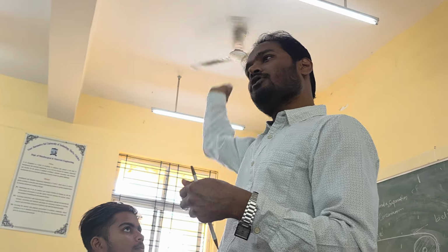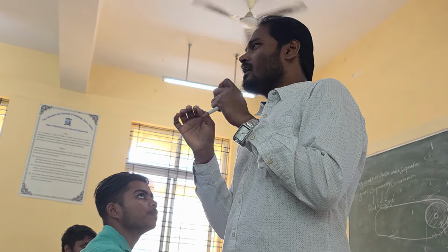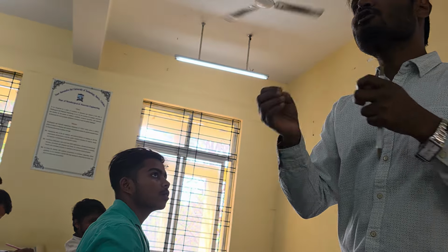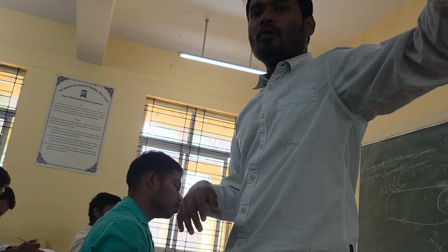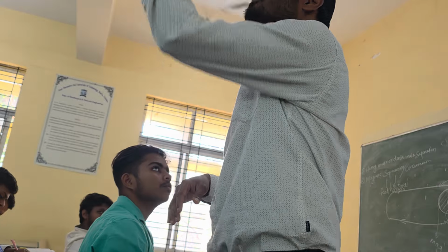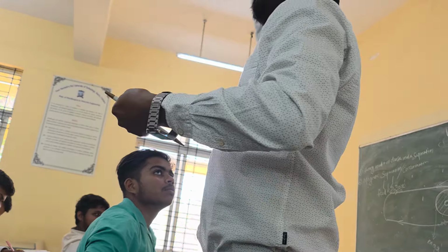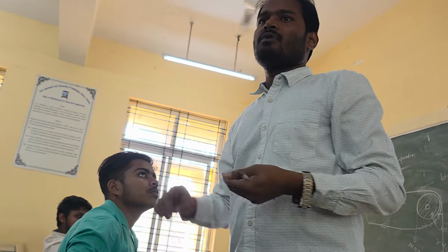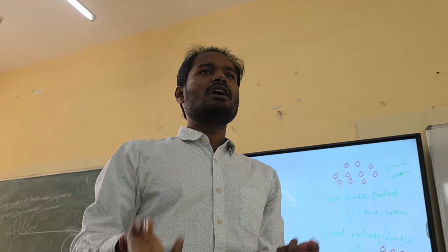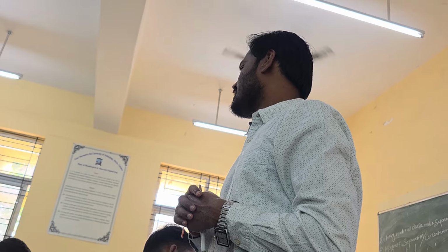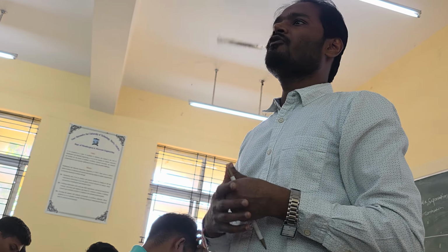That is called heavy dust loss. You will lose a lot of material because the hot blast is moving up from the bottom and you are feeding fine particles from the top. So fine particles will be carried away by the moving blast. You cannot charge fine particles. You have to charge lump so that it will overcome the resistance of the flow of your hot blast.